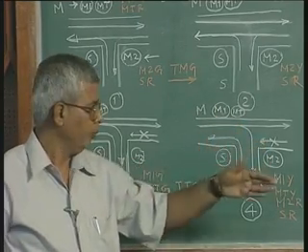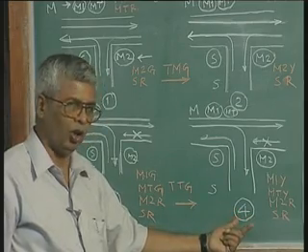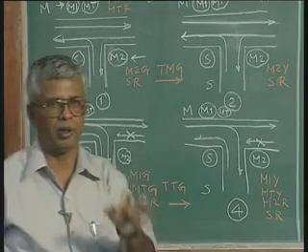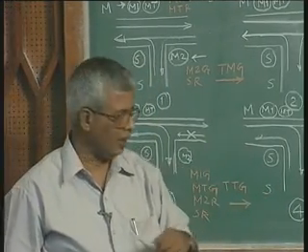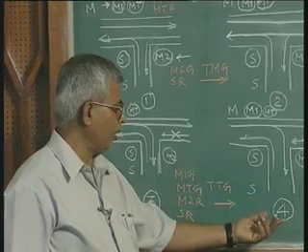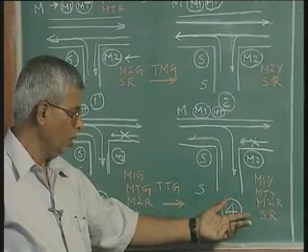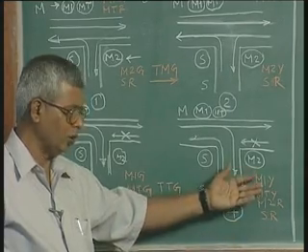Either stop or prepare to stop. That condition is called state 4, which will again last for the period of T yellow. I am not distinguishing between the yellow timing on the main street, the side street or the turning signal. So, T yellow, or Ty, is the time period for which I am allowing this condition to last.